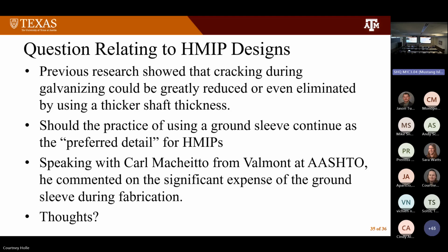All we're trying to do, with the relatively small samples that we're having, is make a note of whether there's anything on a traffic signal pole that might provide the inspector with guidance: yes, I'm going to sample all around the pole, but I really want to focus on this region, because statistically that's where most of the cracks might be. That's all we're trying to provide at that stage.